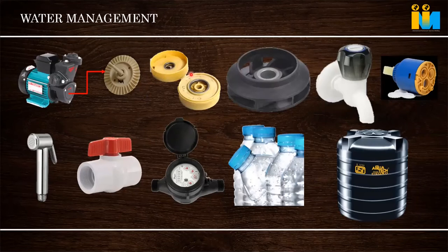When we go for 100 feet depth, the motor pump, you have seen, is like a tube, and its height will be maybe 1 meter. If it goes to 500 feet, then it goes to 3 meters. Stages keep on increasing, so the impellers keep on increasing stage by stage.